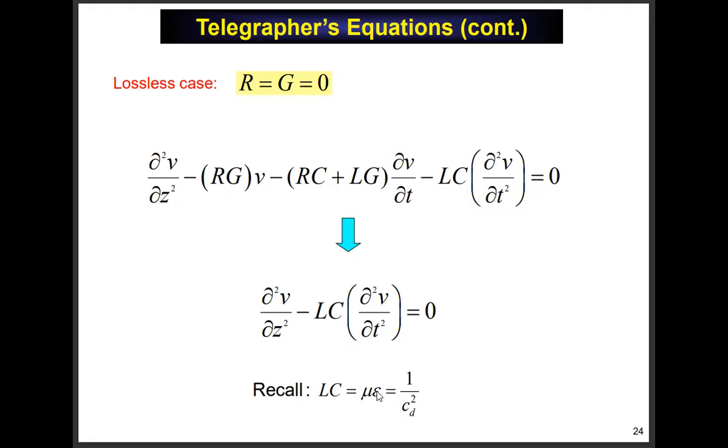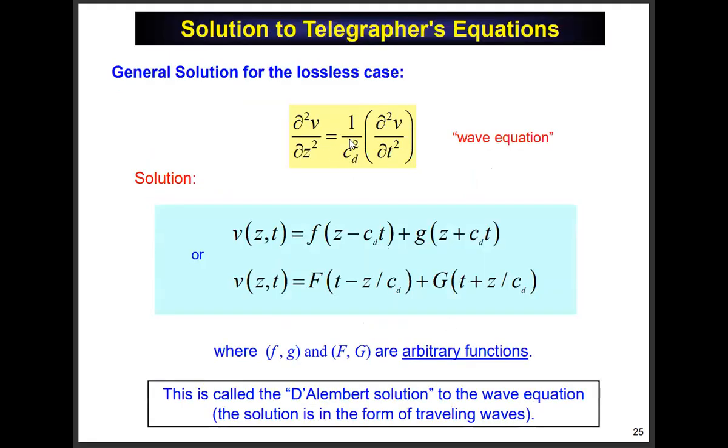In other words, epsilon is going to be epsilon 0 times epsilon R, right? Okay, so anyway, this can be written very simply as just 1 over speed of light squared. And that'll be the simplest final way I can leave the differential equation for the voltage. And it's called a wave equation because it's going to predict that the voltage travels as a wave on the transmission line. The signal travels down the line, just like a wave on water or a sound wave in air travels, right? It's a wave traveling down the line.